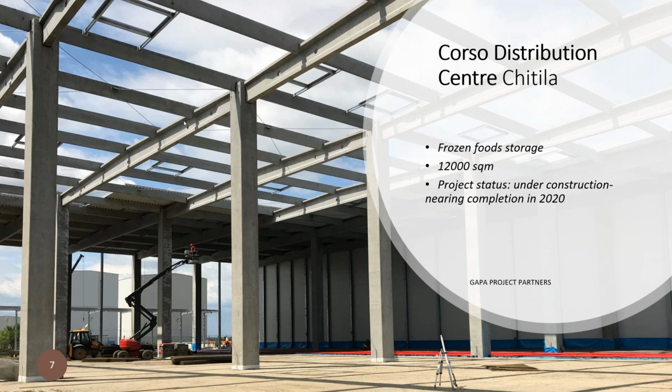Another aspect that is different or special for this project is that it's not the standard box-in-box solution that we see with frozen warehouses, but it's a cold structure solution. So the precast concrete elements are not thermally protected. They will experience sub-zero temperatures for the entire lifespan of this project.